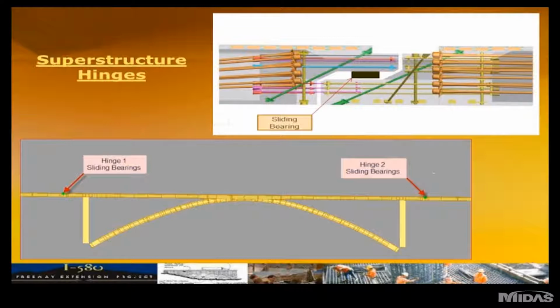And essentially, as I mentioned before, the seismic restrainer pipes were going to go through the two end diaphragms plus the two hinge bodies. Obviously, for a straight pipe, the geometry essentially needs to line up at the time you're casting the upper and lower hinge, critical within a few millimeters.